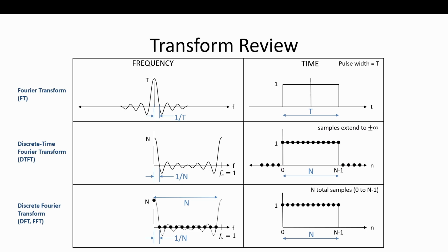So finally, we have the discrete Fourier transform, which the FFT is an efficient algorithm to give us, like the exact result. But it's the discrete Fourier transform. The only difference is it's a finite number of samples in time and in frequency. We have n samples, that's it. We're not extending it out. And so we just get n samples in frequency.